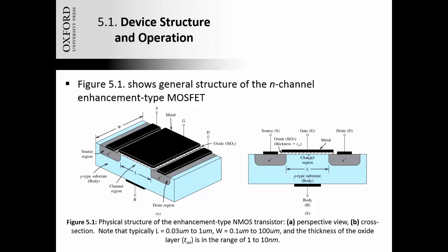Okay, notice also that the drain and source initially are completely symmetric, and so you could call either one of these the source and the drain at this point, because there is a fourth terminal here called the body or the substrate, which has not yet been connected to either the source or drain. Eventually it gets connected over to the left side here, and that's when we associate that well with being the source, because it is the one that is tied electrically to the body.